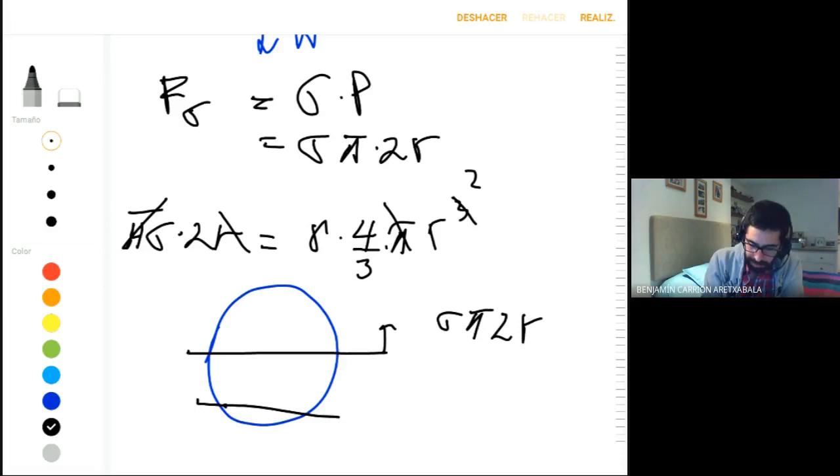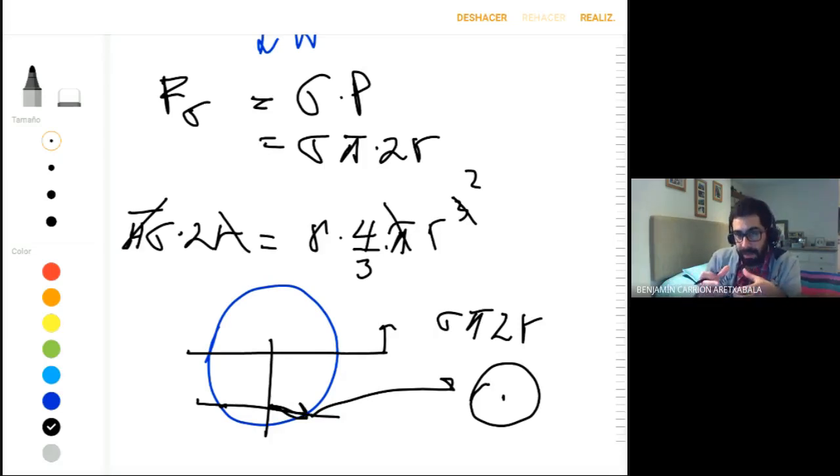If you cut it in a lower position, the circle, let me just draw the circle around, is going to be smaller, because this actual radius is smaller. So the length on which the surface tension is acting is going to be smaller, and it is going to be acting in this direction, normal to the surface.